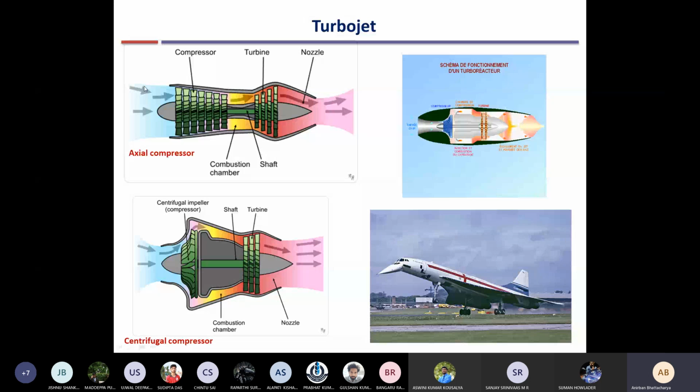of compressor stages. Then there are a large number of compressor stages, maybe 8 to 10, even larger. Each stage is like a fan. You can imagine the ceiling fan you have, it is almost similar to that. The mechanism also is similar. You provide some power to the fan, similarly here also you provide the power. You are rotating it, and it is just forcing the flow from one side to the other side.